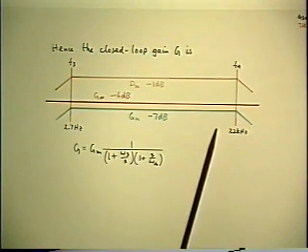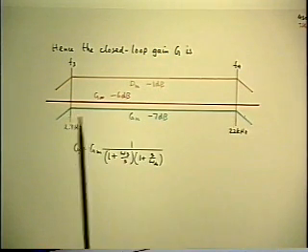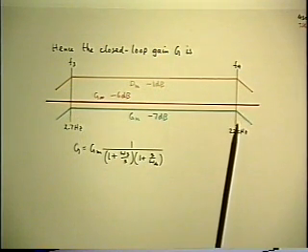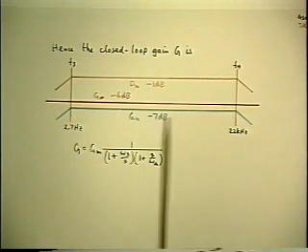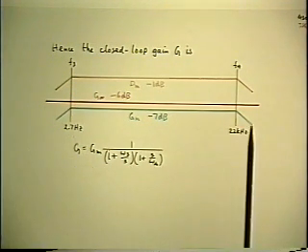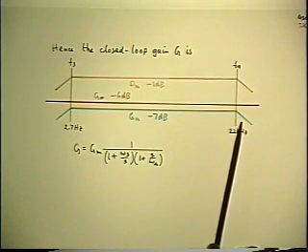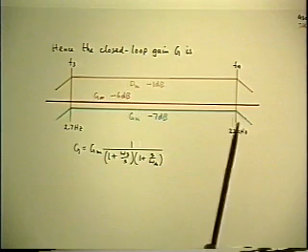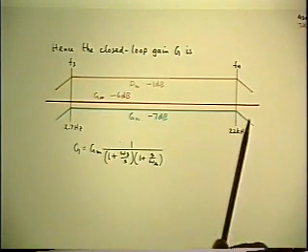There's an important conclusion to draw from this. The two corner frequencies of the actual closed loop gain, these two poles, are the quantities that have to meet your specifications, because your spec calls for a certain gain over a certain bandwidth. So those are the two numbers that you begin with for your design. They have to meet certain requirements. What are those two numbers?